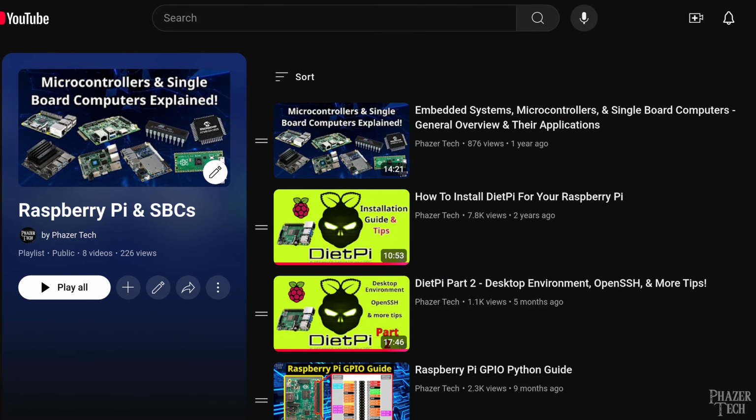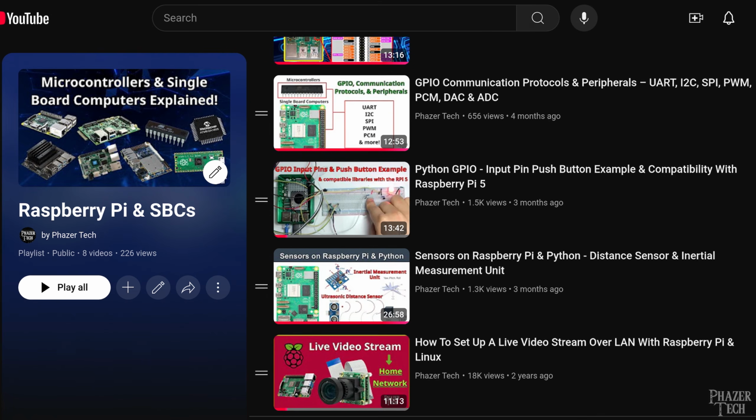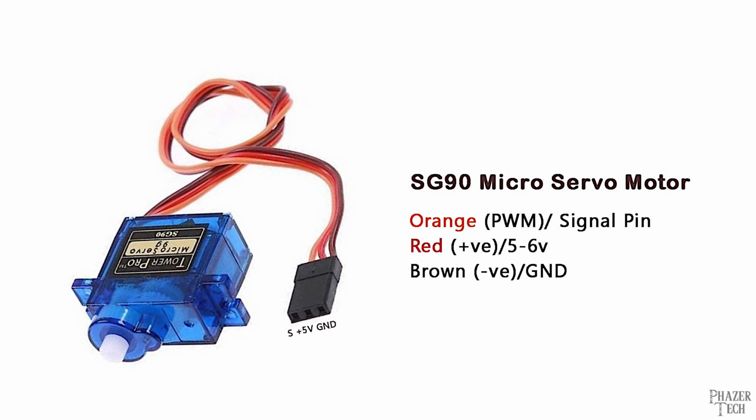Now, like I just mentioned, the next video I have planned for my Raspberry Pi playlist will show how to set up hardware PWM in Python. And I'll be doing several hands-on examples, including one with an H-bridge, and we'll also be showing how to use servo motors as well. It turns out the controller used for servo motors is already built into the motor itself, so all you need to do is connect power, ground, and a PWM signal to control the servo. So stay tuned for that video if you want to learn the details of how to use these devices.